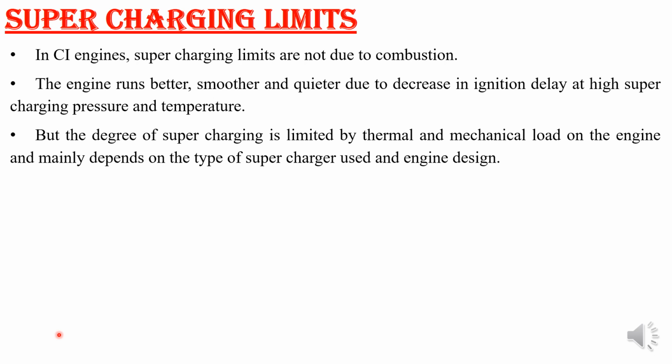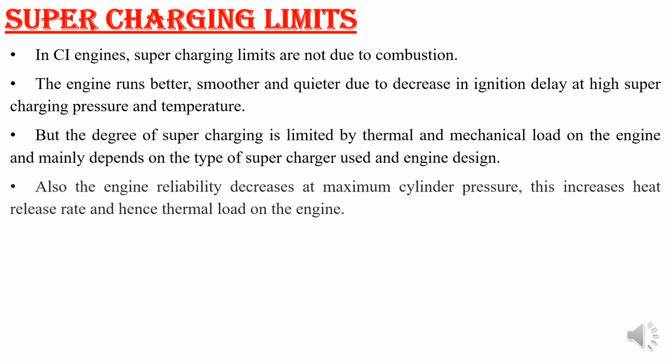The limit of supercharging for the CI engine is reached by the thermal load or mechanical loading. The temperature of the piston and cylinder is very high, which will result in sticking of the piston rings and heavy liner wear. Okay, so that has to be considered.